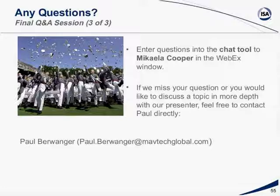Great. Next question. Should an alarm philosophy document include temporary realistic goals for performance, or only the number suggested by the standard? No. You really just want to have what's specified in there by the standard, because temporary by its very nature, this is a permanent document. Your philosophy is a permanent document. There's really no temporary nature to it, and so I would stay with the 150 a day, one every 10 minutes, an hour metrics for alarm frequency.